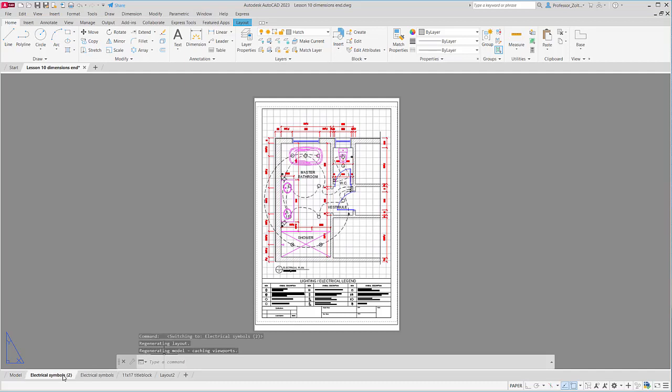This one down here, I'm going to rename. So I right click on it, select Rename, and I'm going to call this the first drawing that we have in this whole series of drawings, which is our construction plan. So I'll call it construction. I have caps on here. Construction. And click off of it. So the construction and the electrical symbols plan is identical.